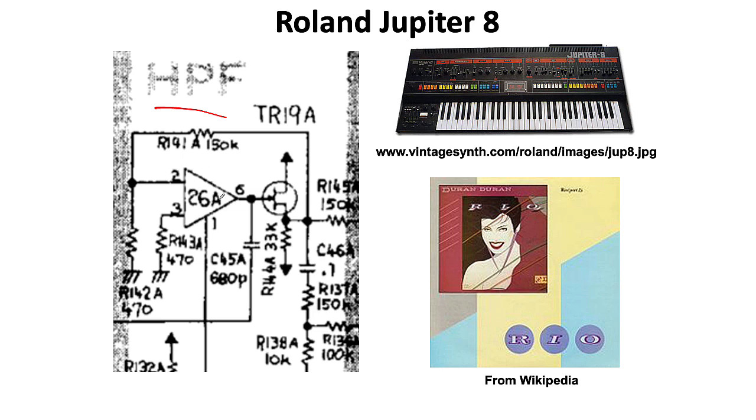So here we have the OTA. Here we have the divide-down ladder of 150K for R big and 470 ohms for R small. The 470 ohm resistor here is just dealing with non-ideal effects of this chip. And here, instead of using an op-amp as a buffer, they're just using a JFET as a source follower.